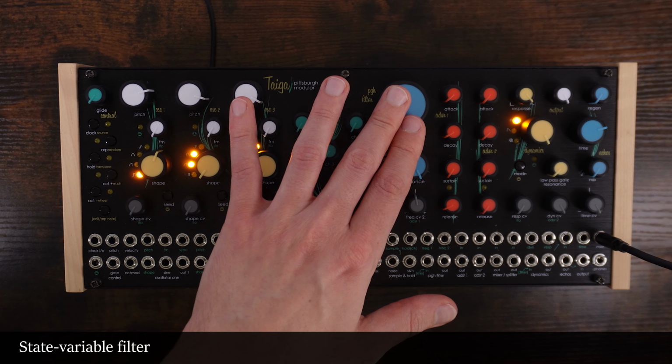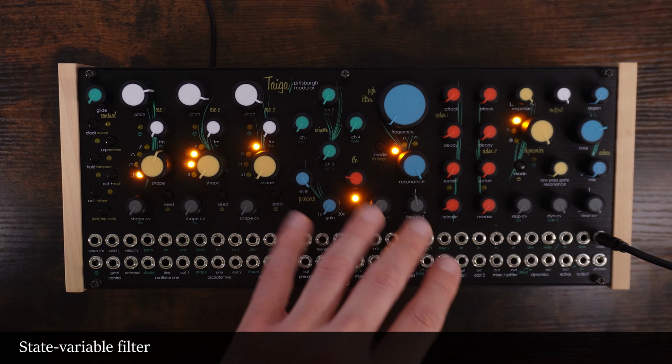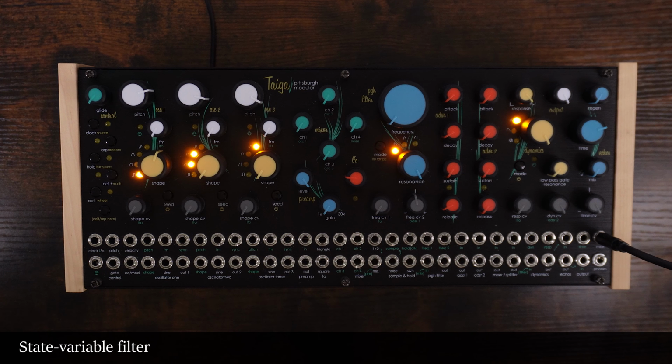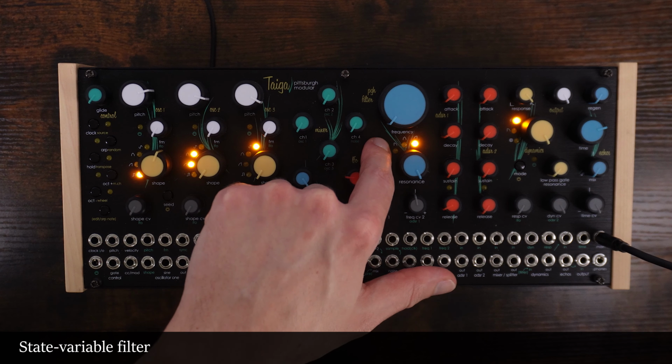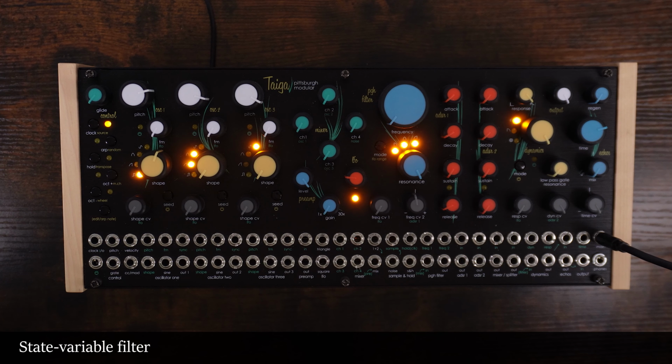The analog 2-pole 12 dB state variable filter is, just like the oscillators, a custom design by Pittsburgh Modular and is advertised as offering a warm organic sweep through the full frequency range. You will see in the sound examples later that the filter is very polite and silky, akin to some Japanese filter designs. The filter offers a low pass, band pass, and high pass function, of which any 2 types can be combined. For example, you could combine a low and a high pass to create a notch filter. And just like for the oscillator waveform, there's a random function that randomizes the filter type on each clock hit.